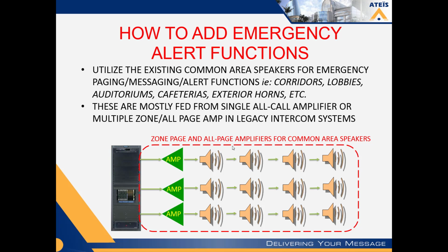One thing to keep in mind is that from one facility to the next, there may be certain areas, like, say, a metal shop or a body shop, or just regular shops or labs, where they may be far away from the common area speakers, where you may just have to add a speaker or a horn or two tapped off the local common area. Just be aware that that may be the case, but that's going to be on a case-by-case basis, and you would know or would have to identify those areas. It's easy to put a speaker wired to the nearest common area speaker just to cover certain dead areas that you may have.